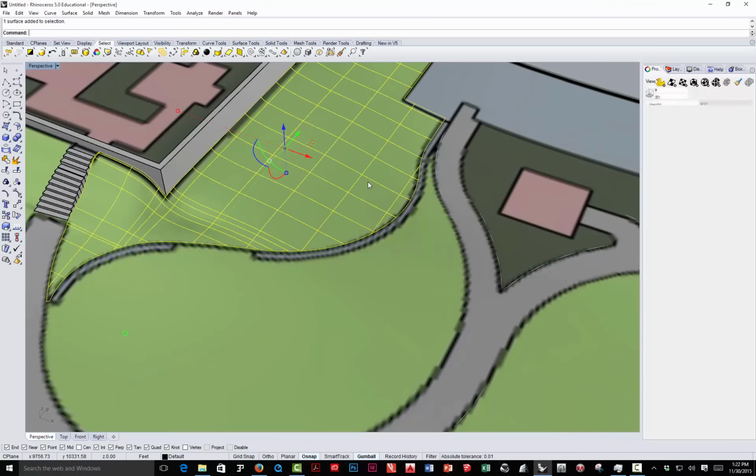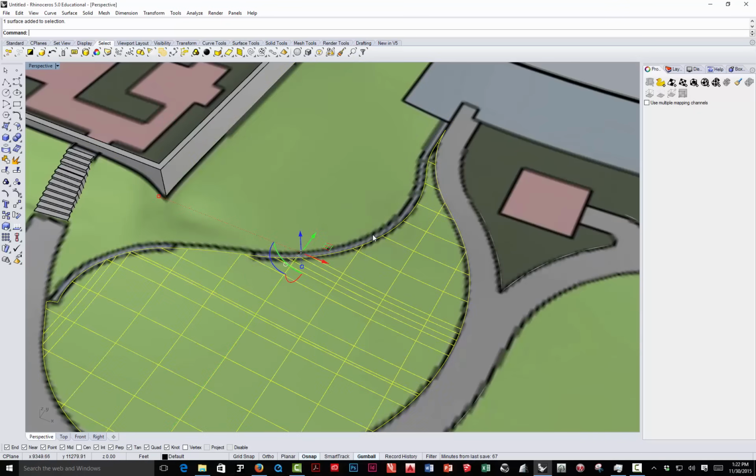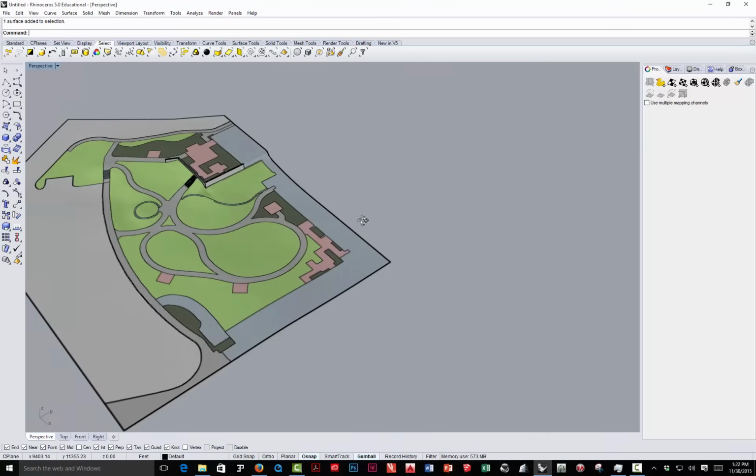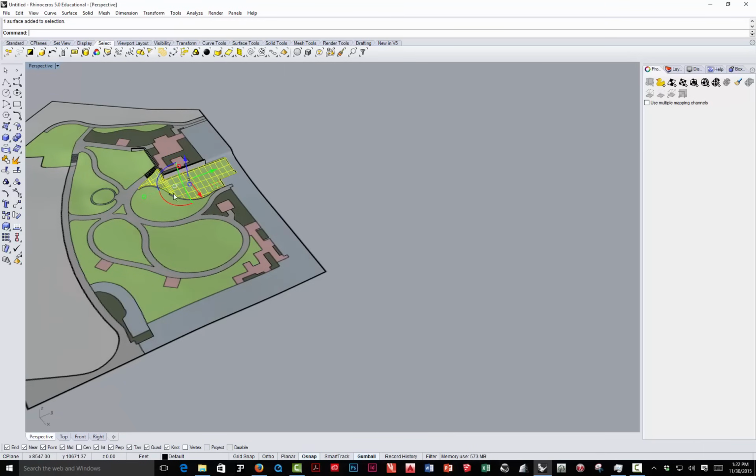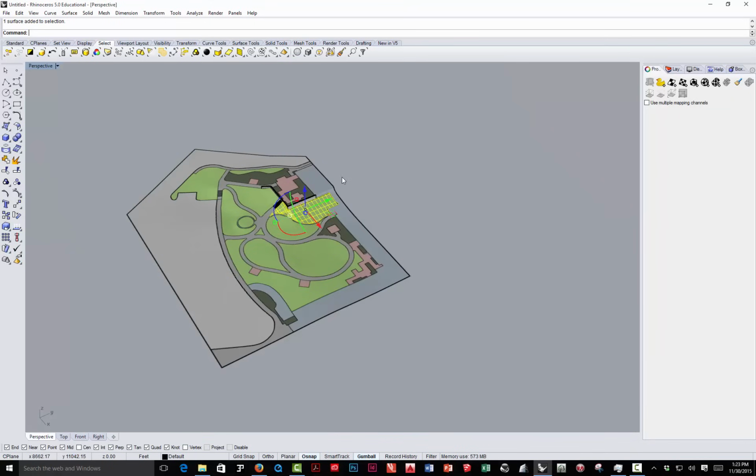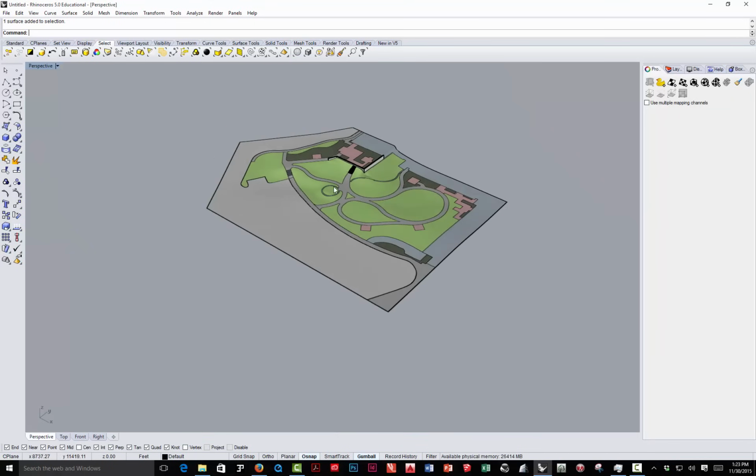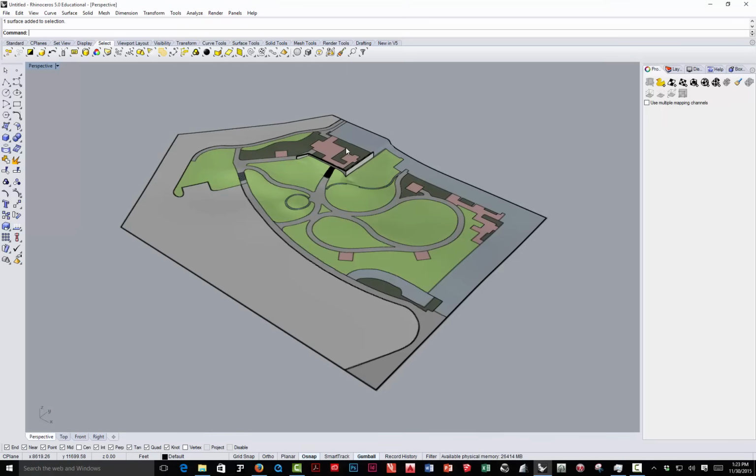And then once we split this, like I have with the wall, later on we can go in there and adjust the control points along here to pull this up a little bit. Since the wall sits up a couple feet, that terrain actually has to come up a little bit. But we can select all those outside edges and just move them up vertically and adjust these control points until we get that smoothed off and fit in there. So anyway, that's kind of the basic process.